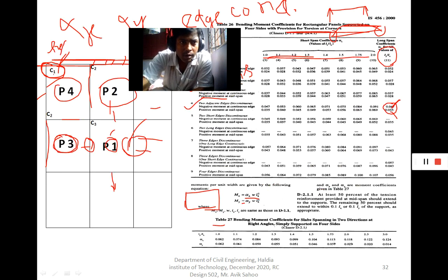You have to apply the reinforcement in 4 layers, and each layer consists of 0.75, means 3/4 of the reinforcement used in the mid span, 0.75 of Ast. I will explain that later when we discuss the design problem.